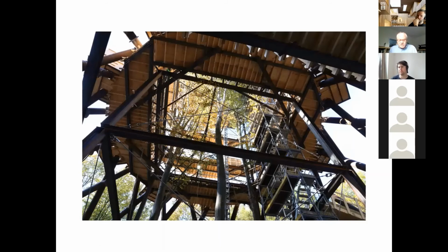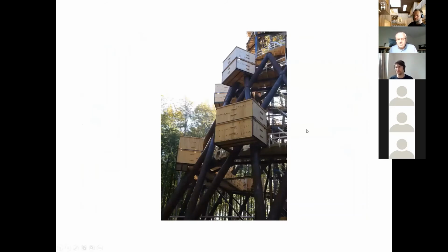After the main structure was erected and welded, in order to work with the welding on site, the erection welding, we constructed some simple small wooden boxes, what we called bird boxes, for the welders to be protected, to protect the welding from wind and so on, and also to be able to walk around the welding positions. They were simple elements which were very easy to move from one welding position to another.